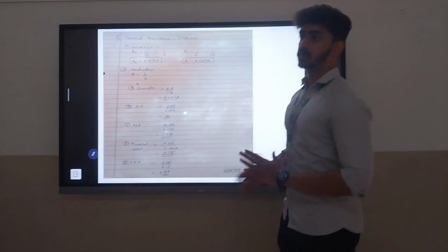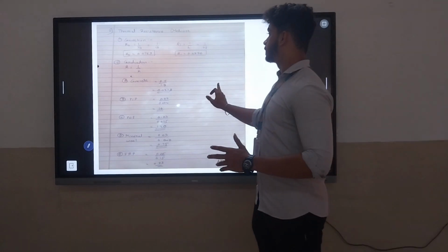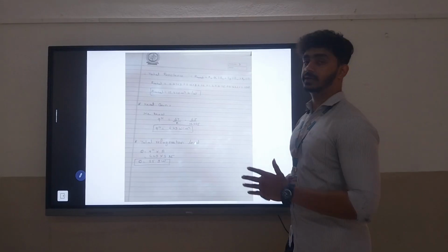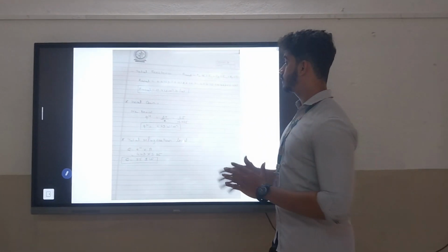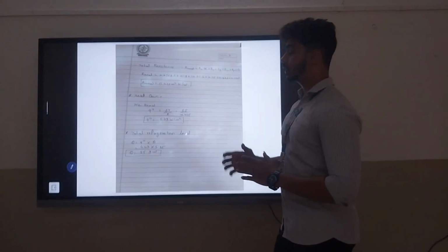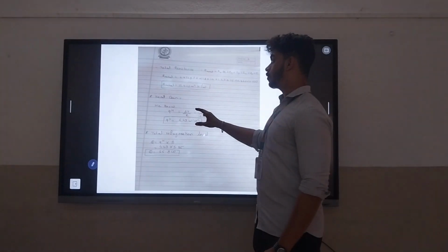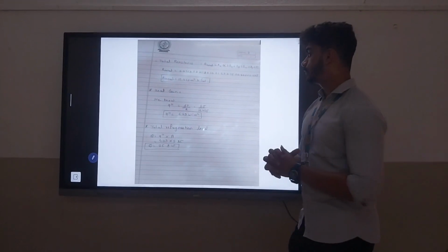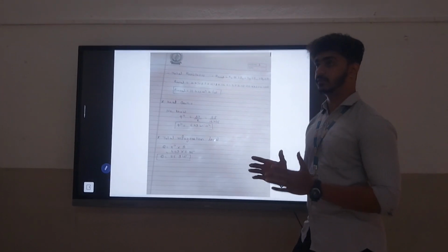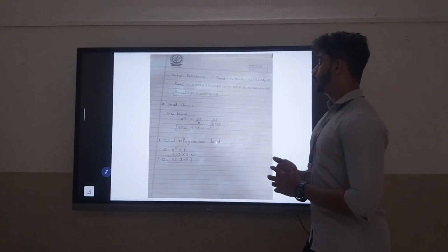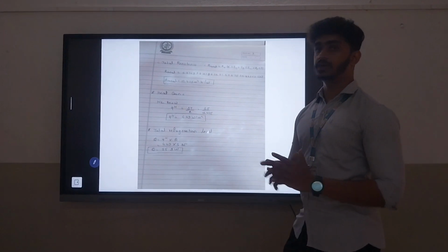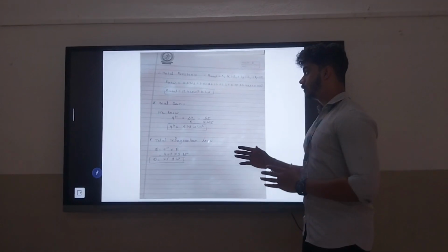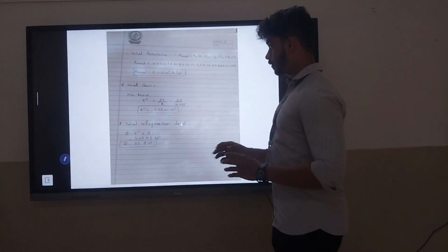We have to calculate the resistances. So now we have to make the sum of all these resistances. The total resistance becomes the sum of the internal resistance, outside resistance, and all layer resistances. That becomes 12.425 meters square Kelvin per watt. So now we have to calculate the heat gain. We know the heat gain is delta T upon R. We have delta T as 55, and R that we have found is 12.425. So we divide 55 by 12.425. So heat gain becomes 4.43 watt per meter square.